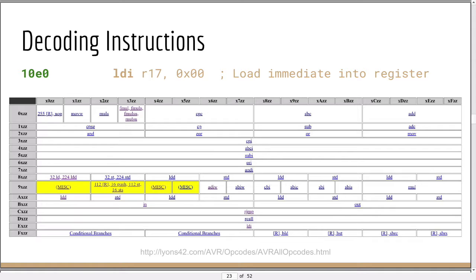So you'll use the first table to look up the general area of what kind of type the instruction is, and then you'll use a second table to actually decode the instruction. This is a pretty neat way, because if you just decode it in table format, you'll easily find out if you missed an instruction or if you have an error somewhere in your instruction decoder.